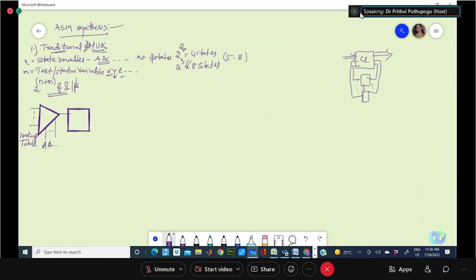And what is the size of the mux to be added? Not only this flip-flop, on this path we will be adding one mux in the mux method. Okay, the size of the mux will be defined by how many states you have in the design, because each state will be provided with one input to your mux.